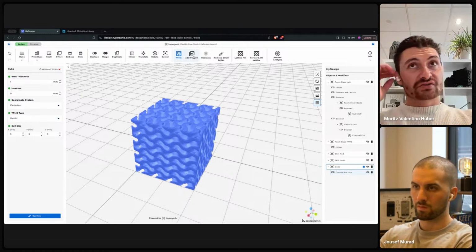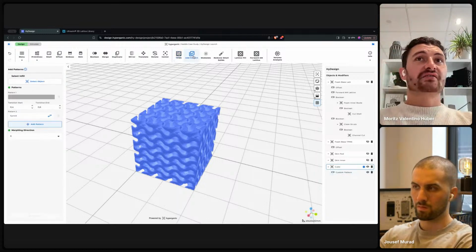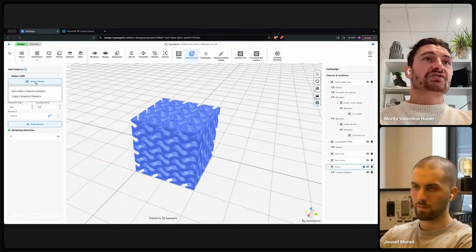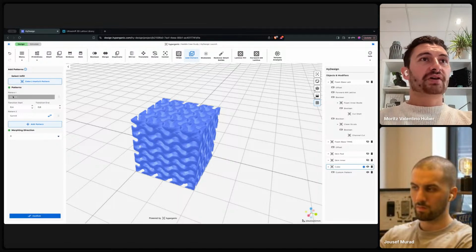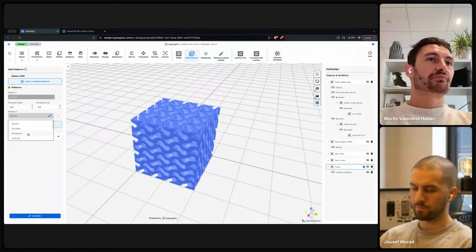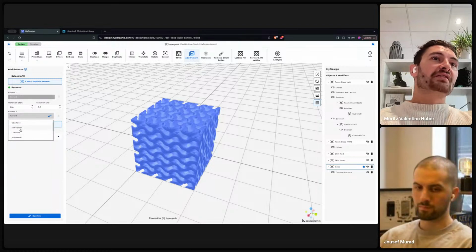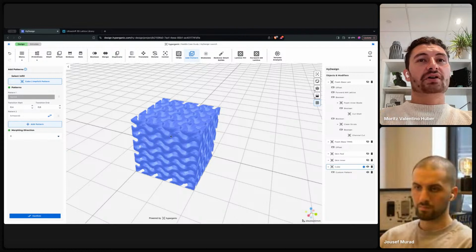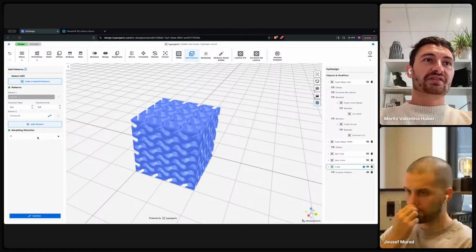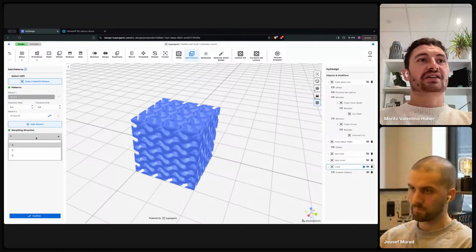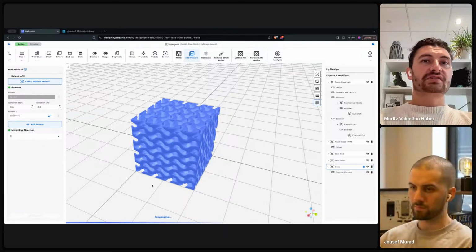And now to just illustrate some of the functionality that is available to the user, such as the infills here, you can merge one pattern, which is here a gyroid, into a second pattern along a primary axis. So in this case, I'm going to merge this into a Schwarz diamond along the x-axis. Confirm this quickly.